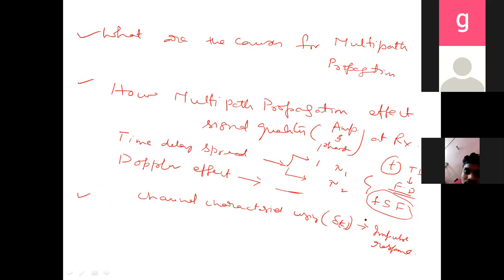Why I have taken this delta t function: as it contains all the frequencies with equal amplitude and zero phase shifts. Okay, and the signal to be analyzed may contain all the possible sinusoids, varying amplitudes and phases. So once I model the channel using the impulse function, which contains all the frequencies, then I can easily predict any incoming new input. So that is how I can create an impulse function. I have seen by adding many sinusoids with equal amplitude and zero phase shift.